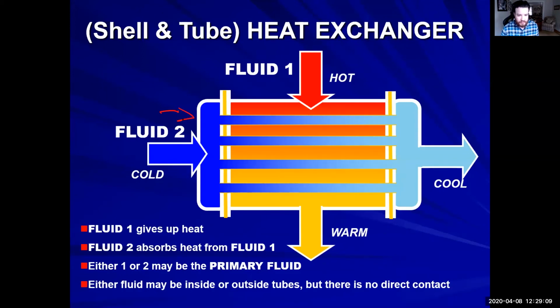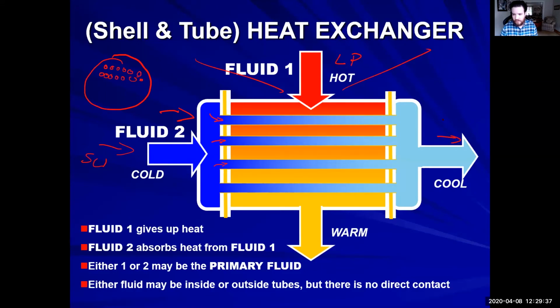If you were to look down this way at the shell and tube type heat exchanger, you would see a massive amount of tubes, all right? So every one of these tubes represents a tube in this drawing, okay? Now, this on our condenser is our LP turbine right there, and this is salt water going in and then salt water overboard. And then this is our condensate.